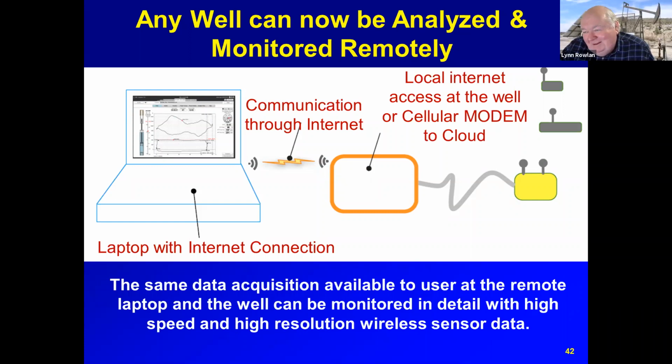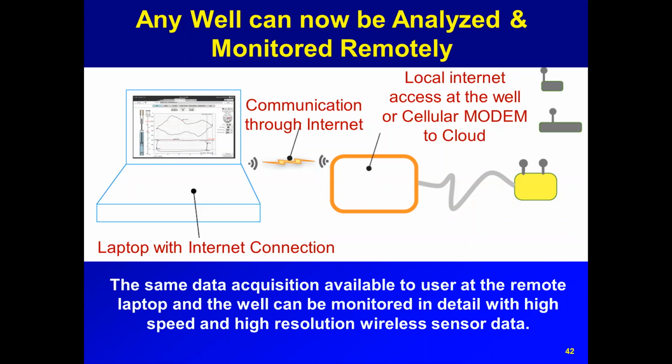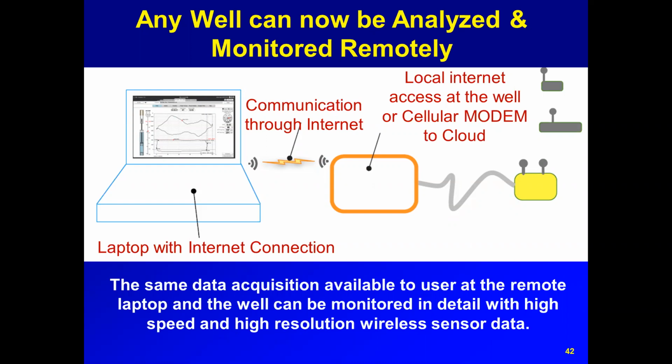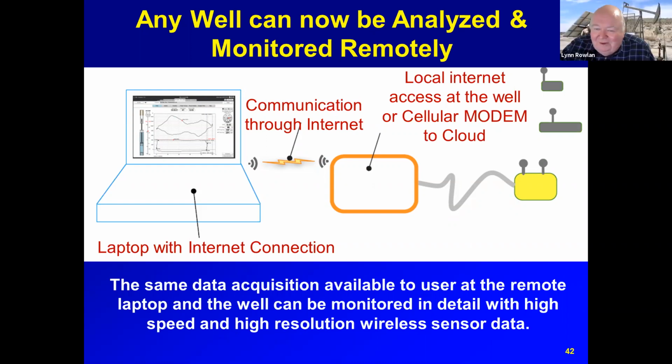A second of data is about 600 to 700 feet. So if the well has a fluid level deeper than 700 feet, then the computer will probably pick the right liquid level, or it might pick the second liquid level echo. It's another 700 feet down, and you still have to go look at it and move the indicator for liquid level to the first echo. So the high fluid levels are harder because the software normally can't automatically pick it, and so you have to.